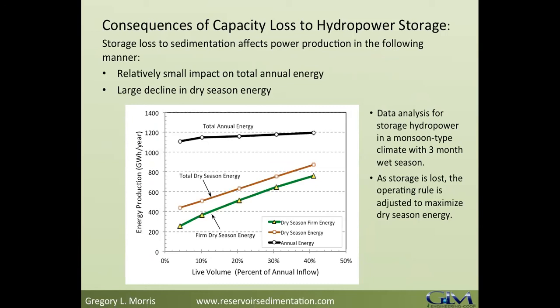And this is an issue, obviously not just in the United States, but all over the world. In most countries it is an issue. One of the things you probably need to consider when you address this is that you need to look at the river upstream of the reservoir versus the river downstream of the reservoir, rather than looking at the river downstream of the reservoir pre and post sediment release, because your pre-sediment release situation is entirely artificial.